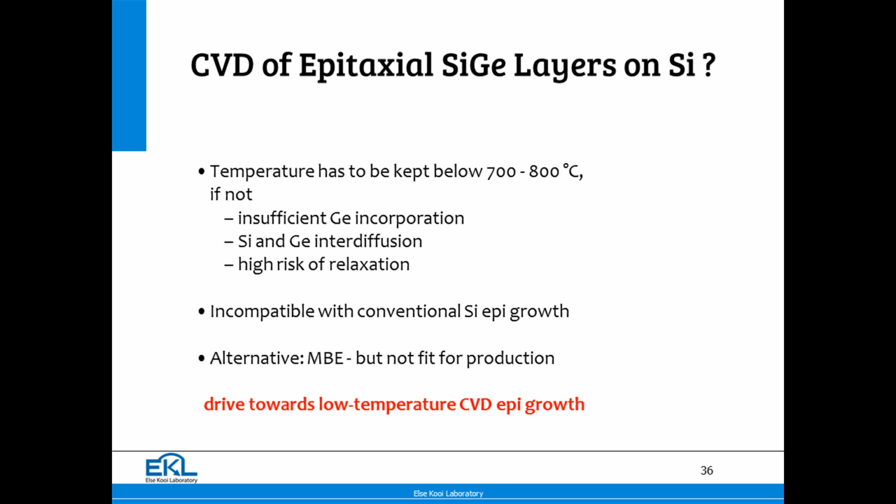He built himself a UHV CVD reactor, and he indeed managed to grow silicon germane epi in CVD mode, kind of LPCVD, UHV CVD. It worked. Those reactors were sold. But there was another opportunity, another possibility. Ironically, when that happened, the reactor that could do it all existed already. Early 80s, it was predicted that MOS, I mentioned it, that MOS needed epi.